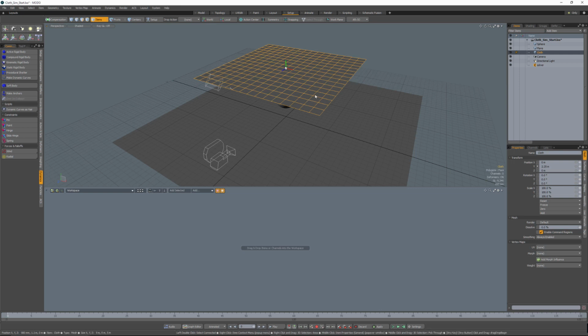It doesn't do us any good to start with a massively dense grid just right off the bat, because as we're adjusting some of the initial parameters, we're going to see that a lot of those are going to apply at any resolution. And then once we add the resolution, what that's going to add in is a lot of the detail and the nuance that's going to make it look more clothy. Yeah, it's a word, clothy.